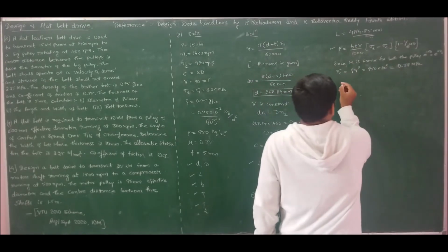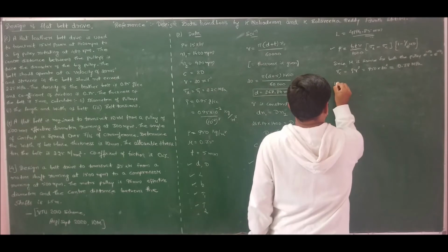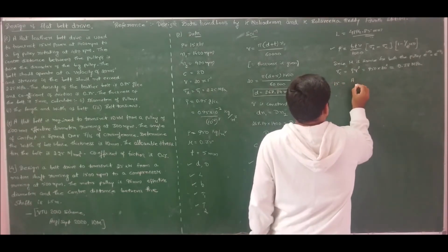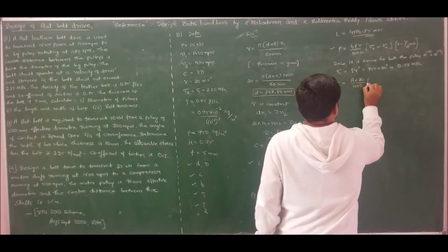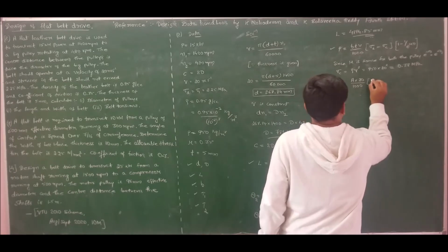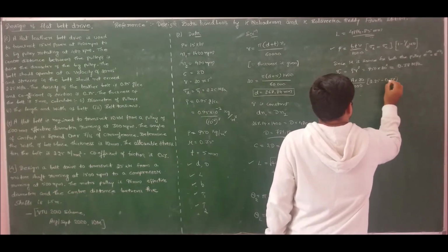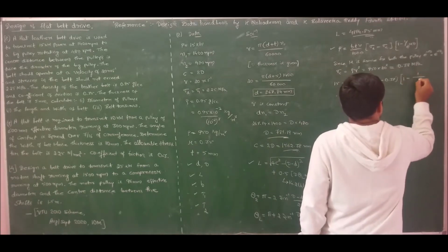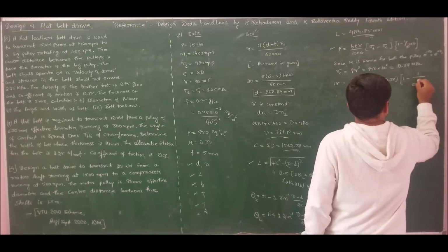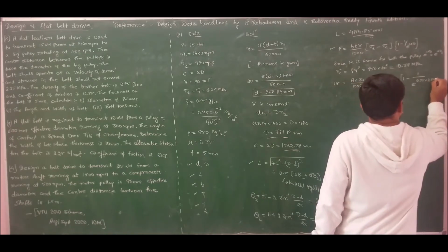So we know all the values. If I substitute and solve, power is 15 kilowatts. Therefore 15 is equal to B into T, which is area, into velocity 20 divided by 1000, times direct stress. The design stress should not exceed 2.25 minus 0.38, into 1 minus 1 by e to the power of mu, which is 0.35, into theta, which is 2.8115.